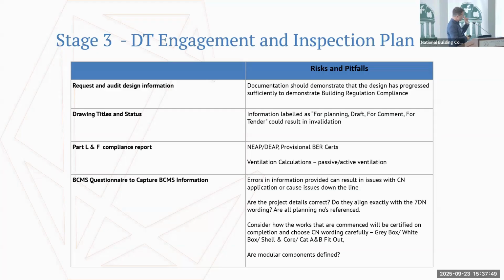If your development has a basement, multi-story basement, a bulk dig, just be mindful that bulk digs can trigger a commencement notice as well. There are interpretations out there that it's only a hole in the ground, it's not permanent works. There are other interpretations from local authorities' perspective that it does trigger a commencement notice. So that's when the bucket goes into the ground to dig your hole, rather than you pouring your first section of concrete. Same goes for secant piles as well.